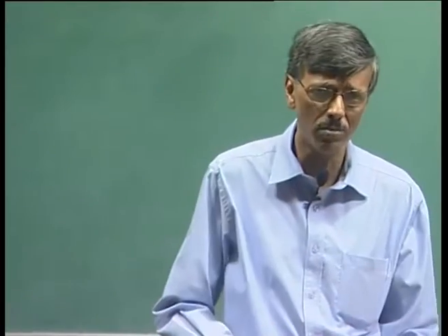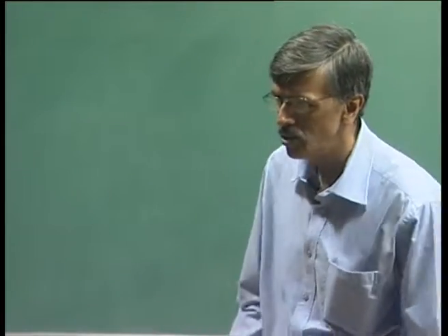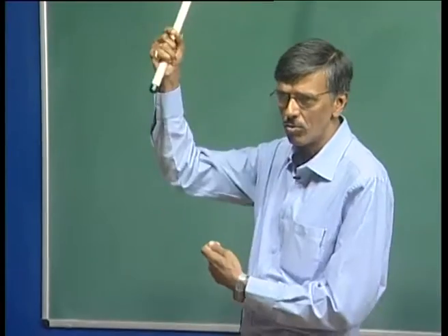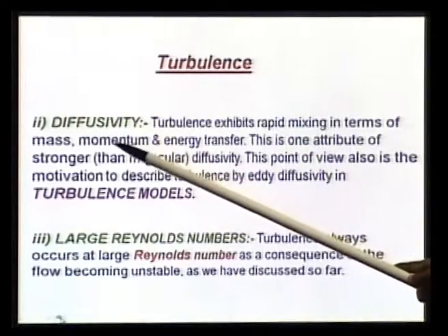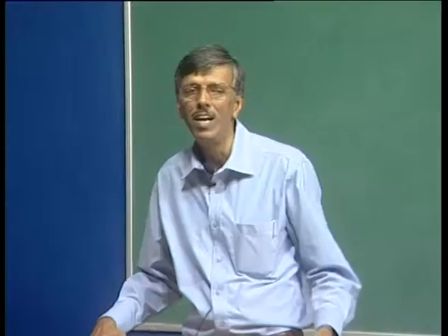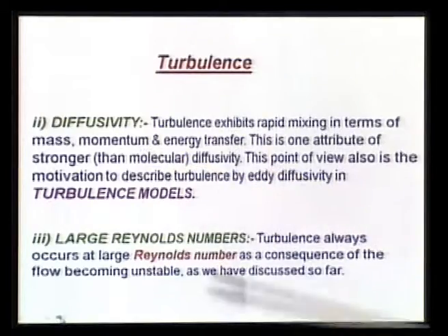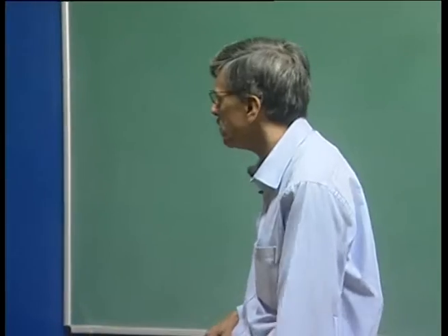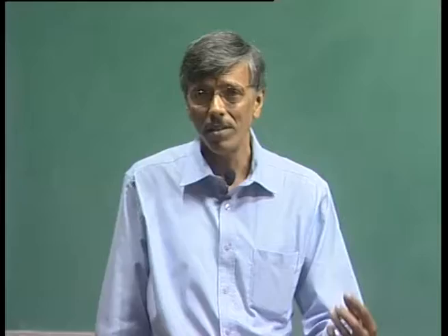At the same time, when I see a shear layer developing, the flow is undergoing transition and becoming turbulent, and what do I see? Thickening of the boundary layer. So, what is happening? The mixing is occurring over a larger wall-normal distance. That is what we are talking about: enhanced mixing of momentum. And of course, when mass and momentum are transferred, that would lead to energy transfer too.